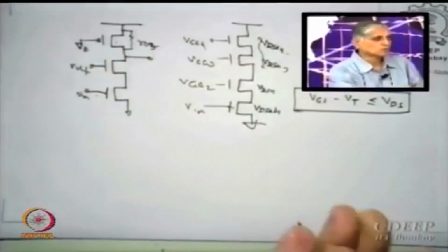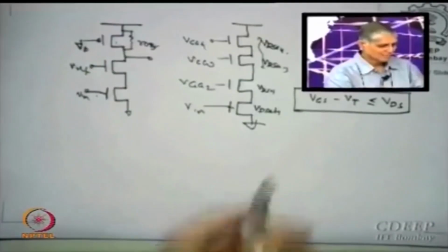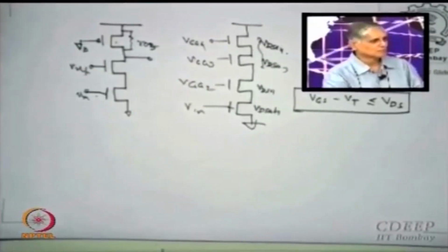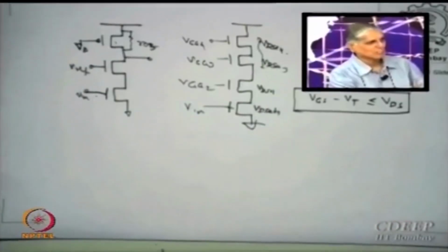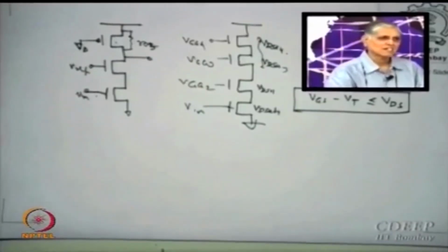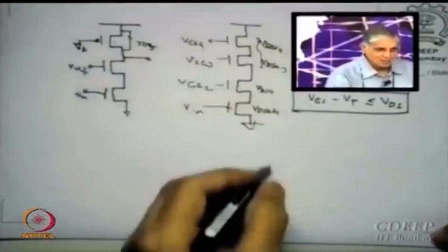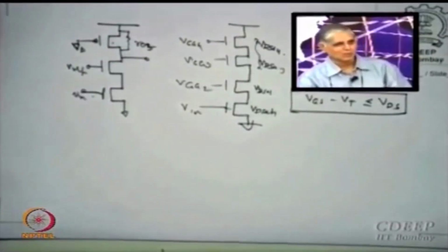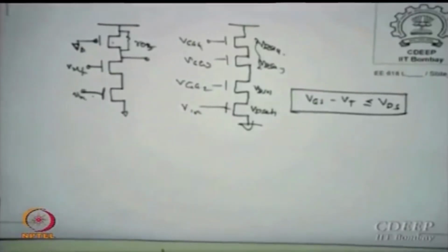For RO boosting you did 4, RO has got what you wanted, a good current source, everything you say achieved. Now you have an issue that there are 4 VDS in series, is that correct? The minimum you have is VGS minus VT, VDsat, one value. Typically how much is the excess voltage? I said 100, 200 millivolts. But now you have 800 millivolts, your supply is 1.2 volt or 1 volt at times, to keep it saturated, your headroom is practically nil there.